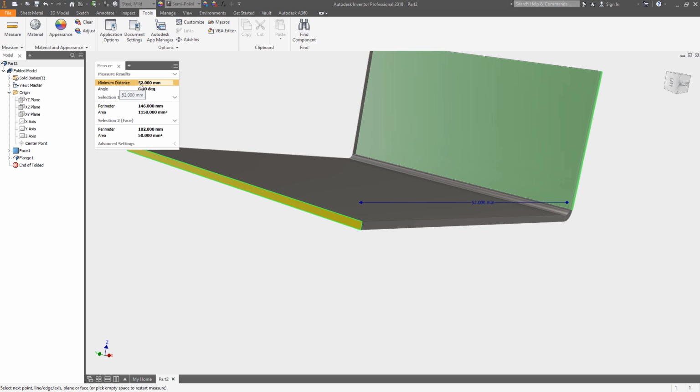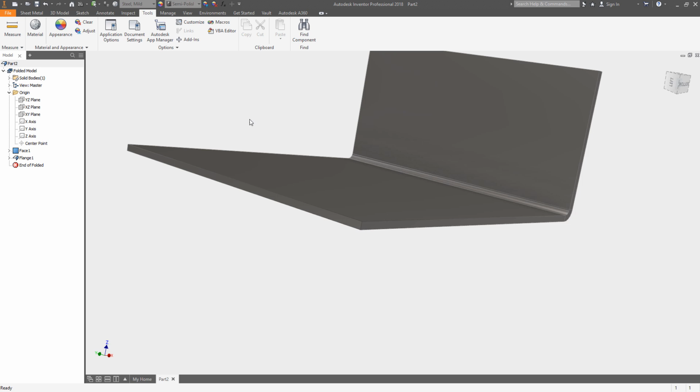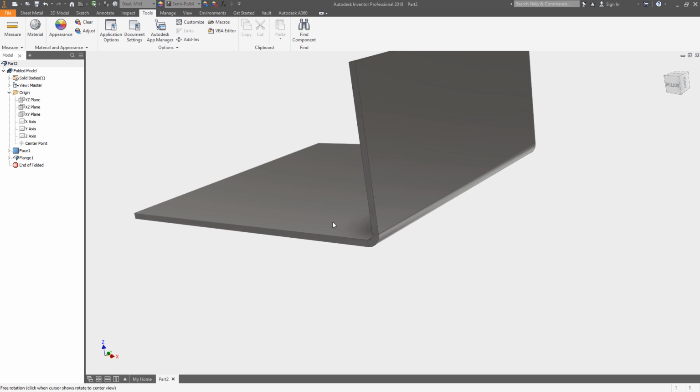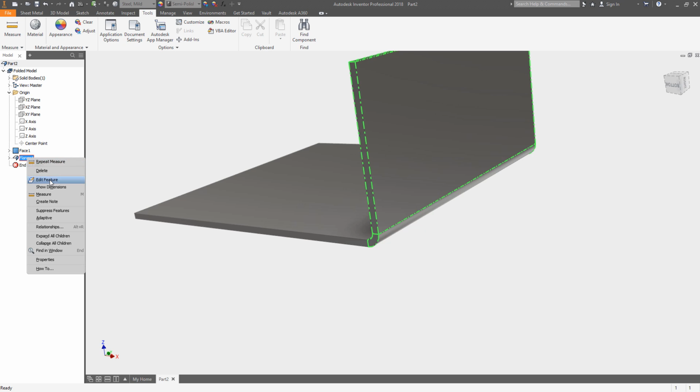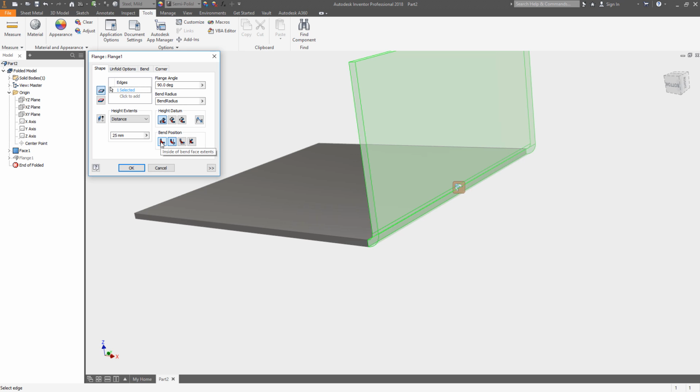And if I continue to do this as I'm creating my component, you could be halfway through creating your sheet metal file, and next thing you know, this thing is 56 millimeters when it was only supposed to be 50, depending on how those offsets get pushed when you're creating these features. So be really aware of what's going on and the direction when you're creating this. So I'm going to go back to here. I'm going to move this to the inside.